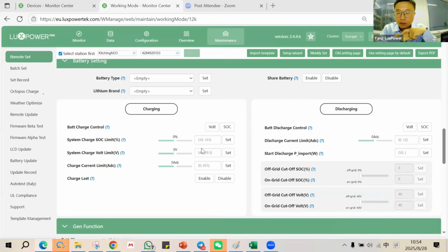They can change everything. So if that case happened, you need first of all to check if the charging limits are the same in your BMS. If your BMS says the charging voltage is only 50 and here it says 56, then the BMS, of course, is most important. It's the main control for your batteries, so it can only charge to the 40s.